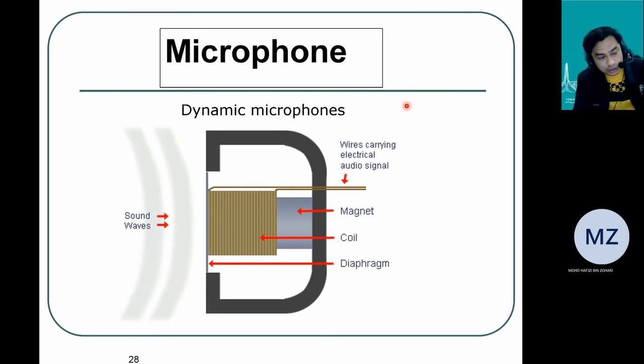The Bourdon tube has a different indicator, which is mostly mechanical, and then the bellows and capsule use a potentiometer or LVDT, and the last one, the diaphragm, uses three types: strain gauge, piezoelectric elements, and also it can use capacitor types of element.